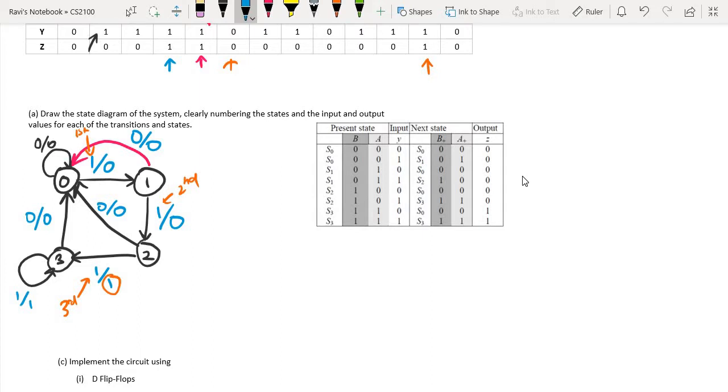In this case, since we know we need 2 bits, we can use all the 4 states and solve the question very easily. If you use 3 states, it is also possible, but just be careful of the don't care conditions. It will be good to check if, after you do a simplification and you have the assigned ones and zeros, it goes back to the idea of a self-correcting circuit, as you saw in the tutorial questions.